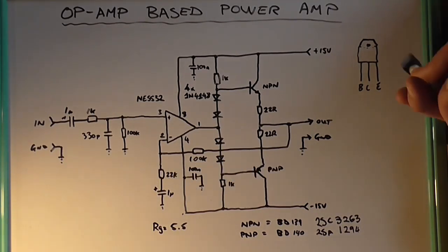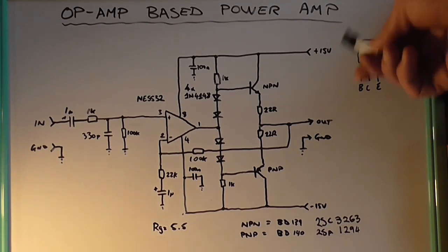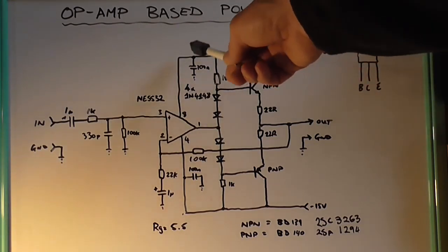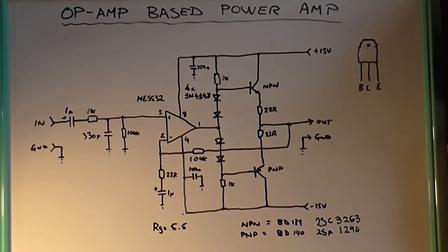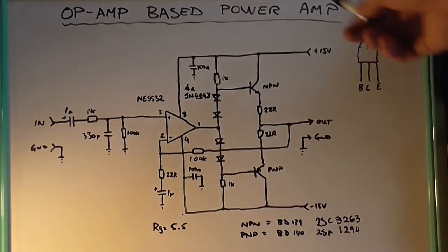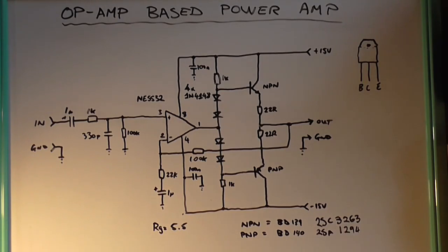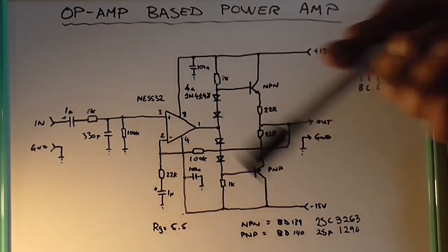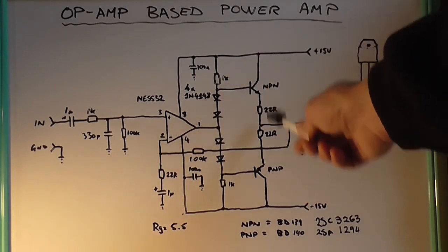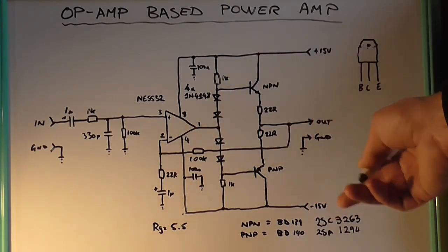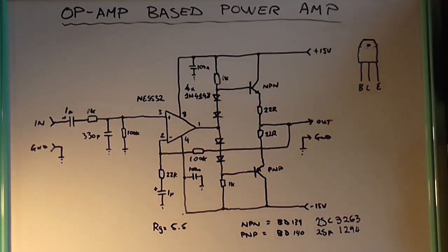Now, I'm not going to modify this circuit to run on higher power and add shunt regulators for the plus and minus 15 volt rails and put 30 volts across these transistors, because really in this configuration, as I previously stated, it's okay, but you'd really want a better output stage to drive speakers to a higher power.